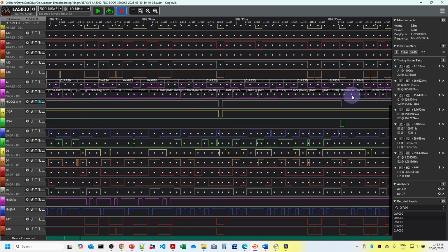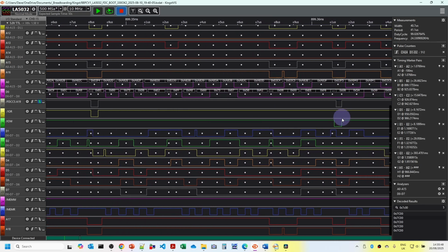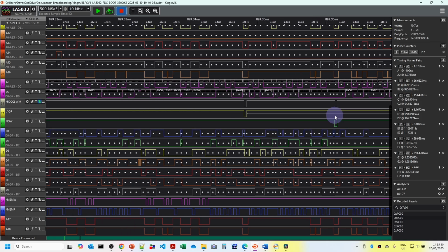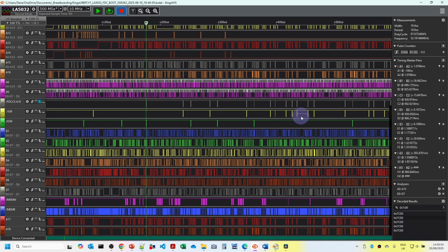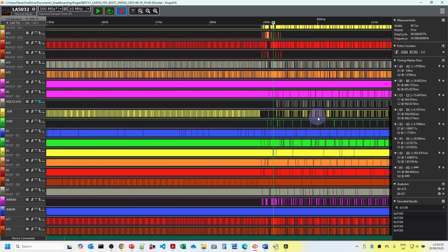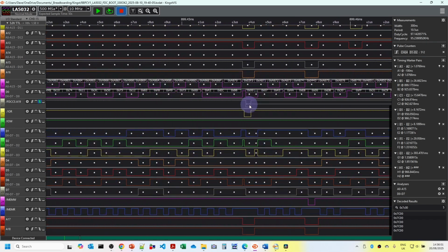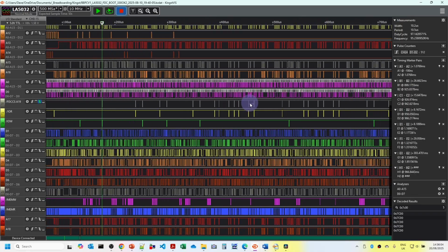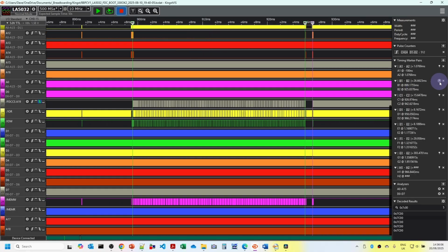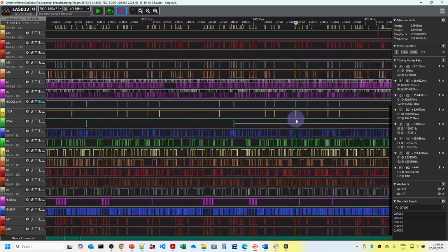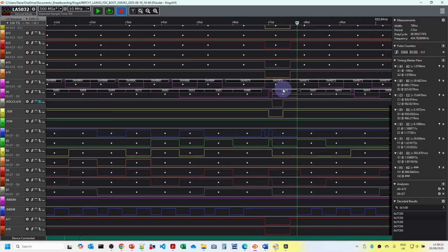And then after this, what we have to do is a sense interrupt status. So this command 8 is sense interrupt, and we have to do this a lot of times. In fact, we just poll this and we keep on getting a value back. The value at the moment here is 0. And basically, when we get to the end of B, we expect the status to come back as 20, which means the seek has succeeded. So what this should mean is that, having done the operation 7, the disk should now be sat at track 0.